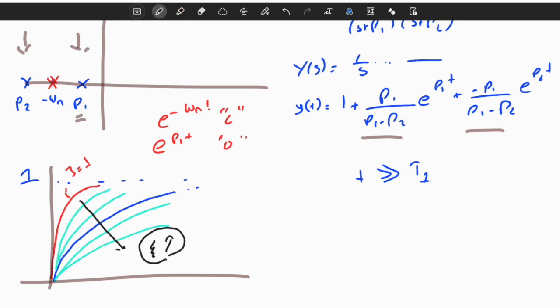Technically, in control systems, we want to reach the steady state value as fast as possible if we don't have limitations on the input and other constraints. So it is desirable to go to 0 faster. It is technically a measure of relative stability. If you go to your steady state value faster, it means that you are more stable, you are faster, and you are technically a better system.